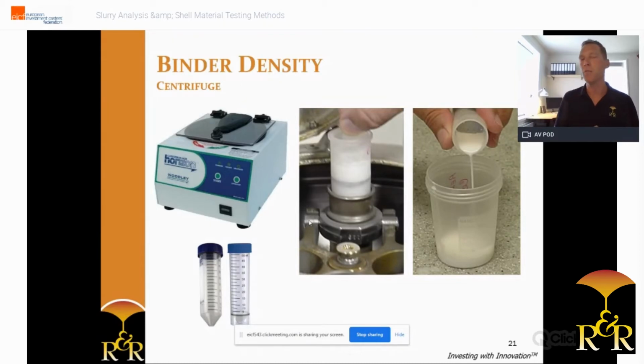And to do that, I always prefer to take a sample of the slurry a few hours or the night before and already let the refractory settle by gravity. This makes it much easier to get a large volume of this binder. Of course, you can take samples directly out of the slurry tank if needed, but it takes more effort and time to spin the binder out.